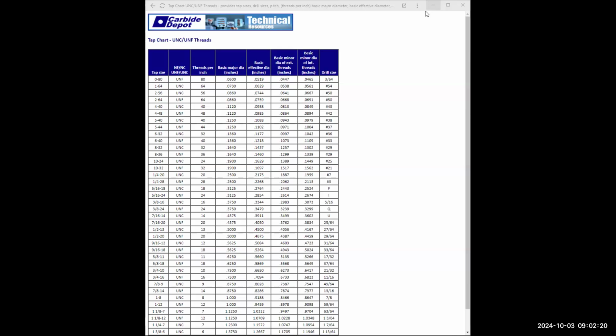Enter, select these lines. Again, Mr. Morris is showing you the hard way first. Enter, type in P for property, enter, type in LT for line type, enter, type in hidden, enter, enter again.